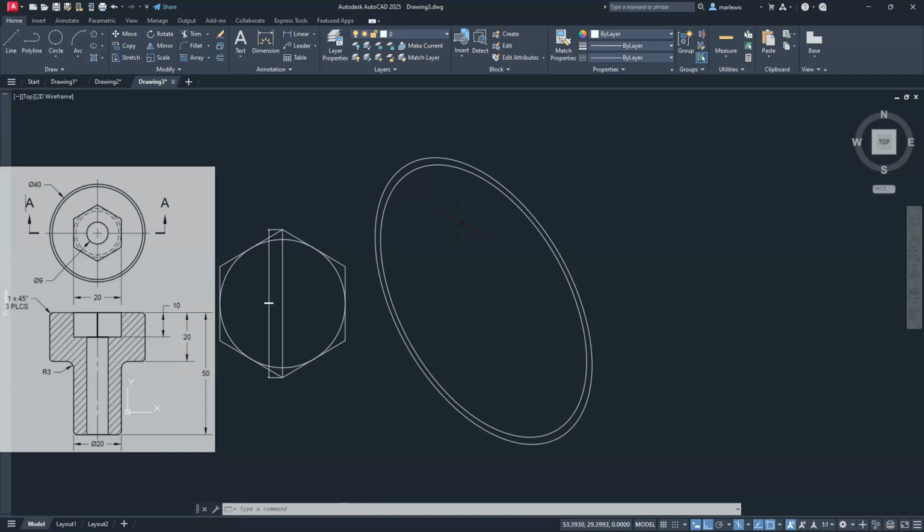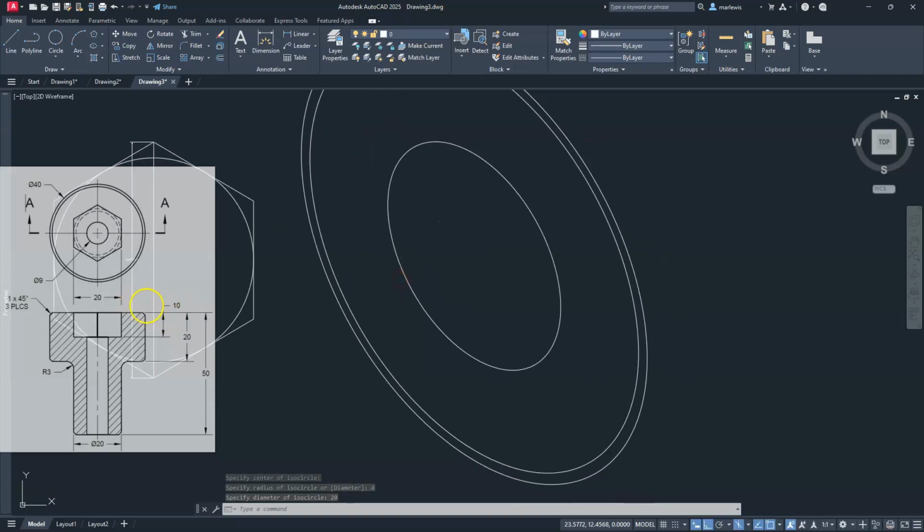And now we're going to go ahead and draw one more ellipse here, or isocircle I should call it. And then I'm going to start constructing my polygon. Okay. So let's go back to the ellipse command, EL, enter, I enter. Let's go and find the center, which is located here. D, enter. I'm going to type in that diameter that I needed, which is going to be 20. Now, I'm going to take this line that I created earlier. So let's go ahead and select that, and I'm going to use the grips. I'm just going to select this blue square in the middle, and then I'm going to go place it right here at the center of my circle.